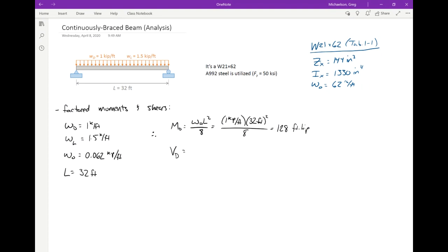All right, so Austin's answer is that's the equation for shear. Now I want to mention something. If you look at the table, this is something you've got to be careful with. It says W, like Austin wrote, W(L/2 minus x). That one's actually an L. It looks like a one, I know, but that's the length. But that is the equation for shear.